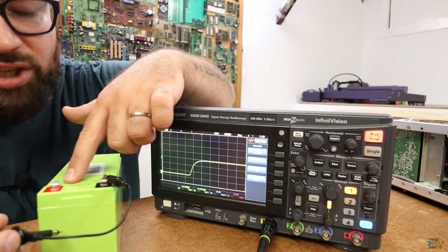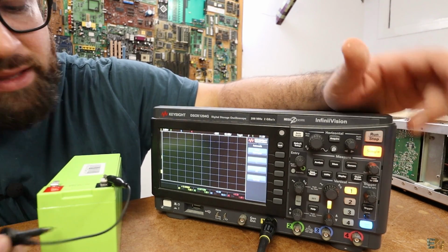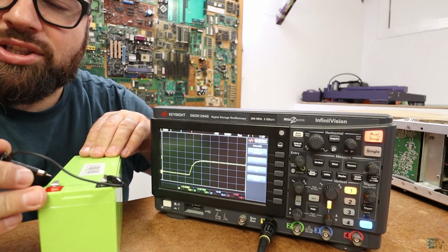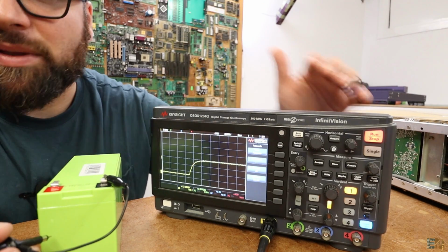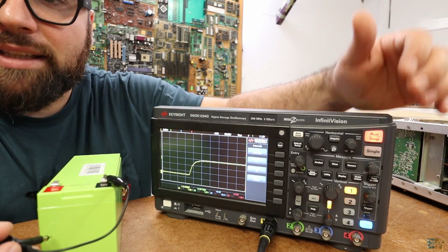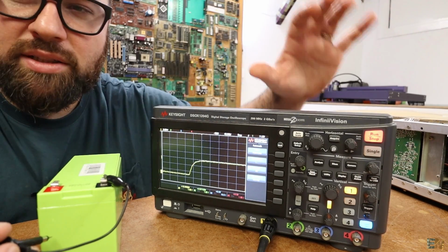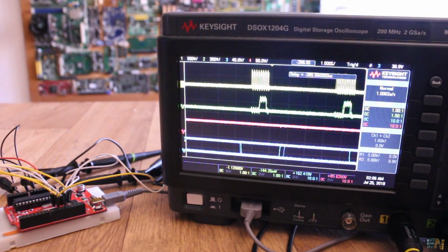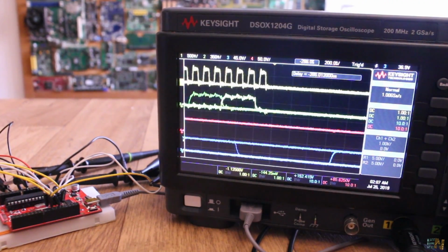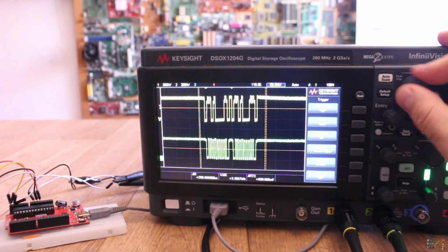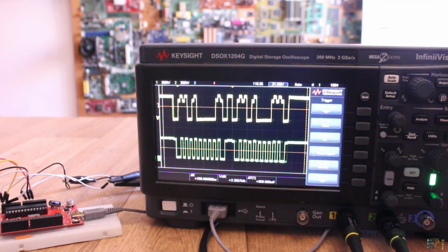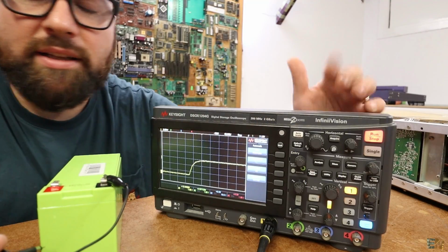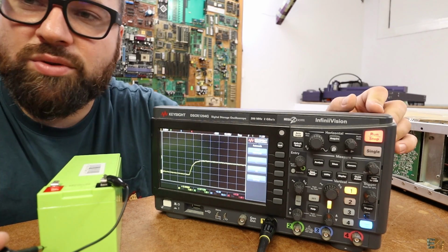So if I want to see that charging process, let me just press it once again. Exactly that moment, when I touch it, it will trigger it and keep it there. So you have the run, stop button and the single one for just a burst of signals. For example, if you are watching an I2C communication or something like that, you just press it once and then you get the entire signal on the screen. And you can place the settings for how long it will record from the signal and so on. And these two buttons are also very important.